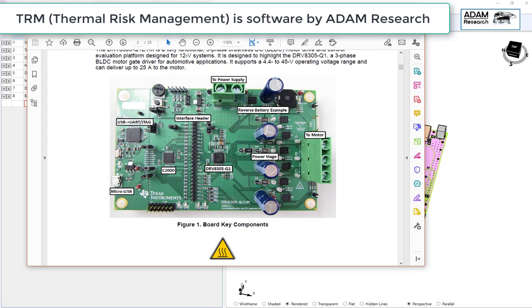In order to have as little user input as possible, we can make the transistors permeable for electric current, and we have the chance to add electric resistance, which regulates the voltage drop and the power dissipation in the MOSFETs. So here we are using the RDS on value. We also use the known values for the ohms in the shunts.